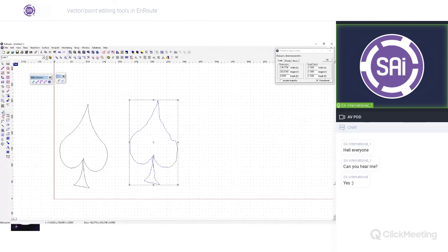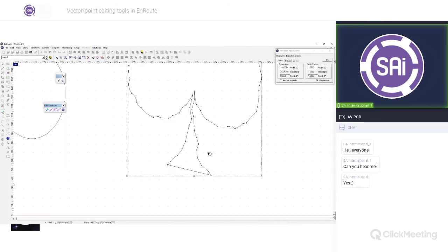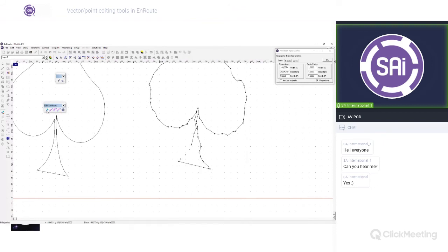And once you select it here, basically I'm going to use the edit points that we have here, the edit contours, and we'll use mainly the edit points, the linearization of a curve section, and the smooth approximation tool for this one. So basically here I would select this part and this part, hit enter, and that will clean up any points that we do not need.